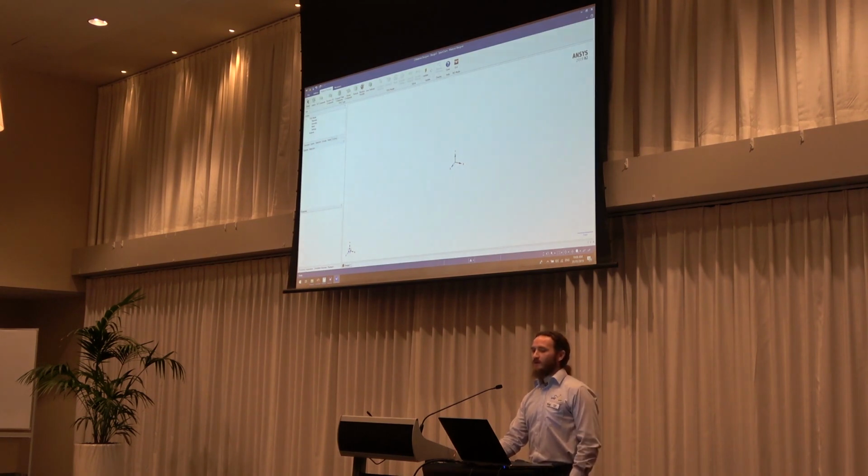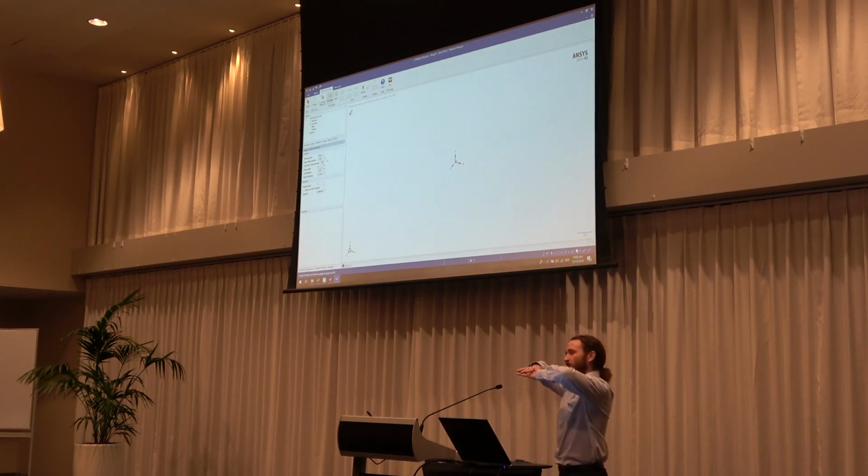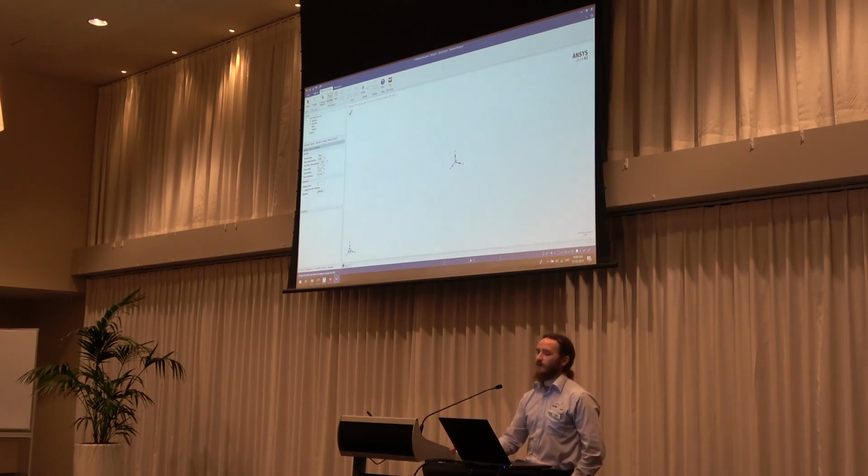So this is it here. We can do lattices, unidirectional composites, random unidirectional composites, chopped fiber composites, a woven composite, which is what I'll do, particle reinforcement, or a user-defined option. So I'm going to do a woven composite. So I'll choose resin for my matrix, and carbon fiber for my yarn. Go to the geometry, so I can specify the fiber volume fraction, whether it's a plain or a twill weave, the shear angle. So when the fabric shears, it'll have different mechanical properties. I'm just going to leave it at 0, and I'll show you other shear angles in a moment. Yarn spacing, the fabric thickness, I'll just leave the defaults at that, and I'll hit the tick.